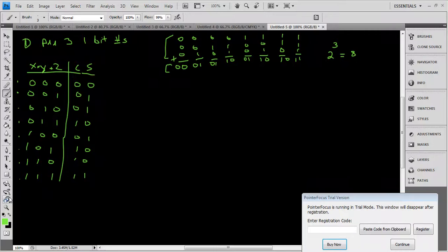Okay? Now, let's make some equations. And yes, as you can imagine, the equations will become a little longer because it doesn't really matter which order you do these in. Okay. Again, but here's the nice thing. No new concepts. Just do the same thing we did before. Go down the C column first, and if you see a 0, skip over it. So don't care, don't care, don't care.